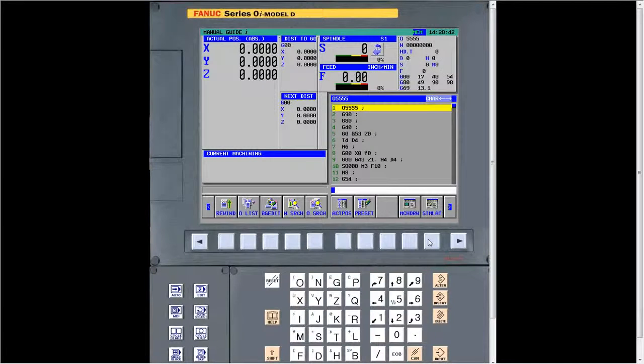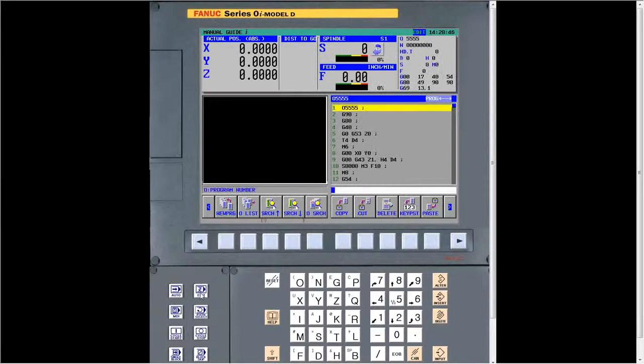Okay? So again, it's very simple to use the engraving, but now one thing you might ask is, say you wanted to do part numbers. It won't let you serialize it. Because to be honest, I've been trying to figure out some way where I could increment the number if you're doing a part number, but frankly, I haven't figured it out yet. If there's a way, I will figure it out. Right, so that's engraving. But again, it's very simple. The main thing you got to remember is get the right tool type, either a drill or a ball nose end mill. That's the biggest mistake people make, is that they don't do that.